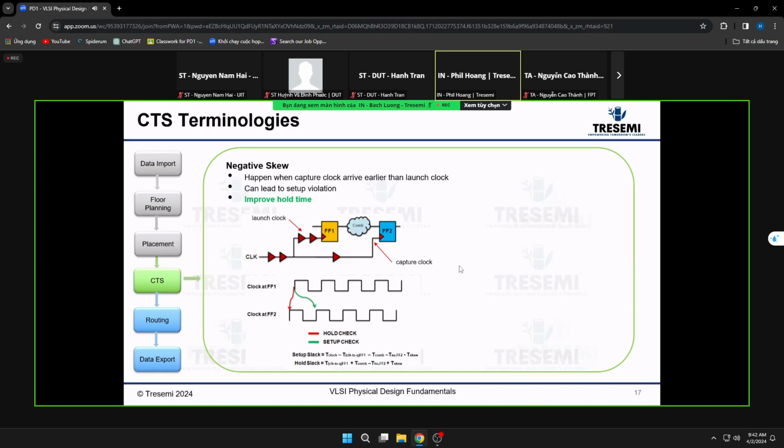Because when you do the clock propagation delay, all these gates are in propagated mode, meaning the common delays will be the same regardless of whether CRPR is turned on or not. But CRPR relates to OCV, which is an advanced concept. Maybe it's not covered in this basic class.